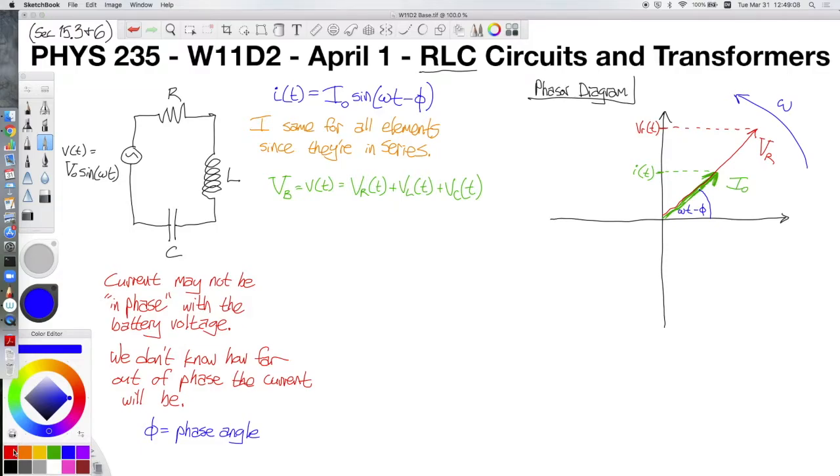Then we can start to draw arrows on this phasor diagram for our other circuit elements, other than the resistor. As we know from the Eli portion of our Eli the Iceman mnemonic, Eli says the EMF peaks before the current for an inductor, which means that the EMF for our inductor is going to pass the y-axis before the current.